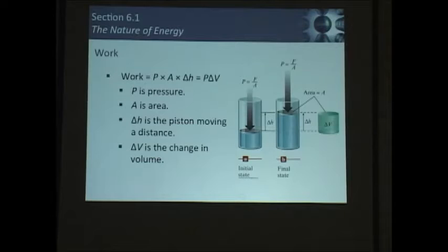Now, you can see here that there are two kinds of process that will take place. Assuming there is gas inside the cylinder, when you apply pressure, you're compressing the gas. And if you release the pressure, essentially it should expand and revert back to its original position. So what is going on there is the two types of work that we are relating to. When you move the compression work from a high volume to a lower volume, that is work done on the system. And when it's work done on the system, it is going to be positive, and work done by the system is going to be negative work.